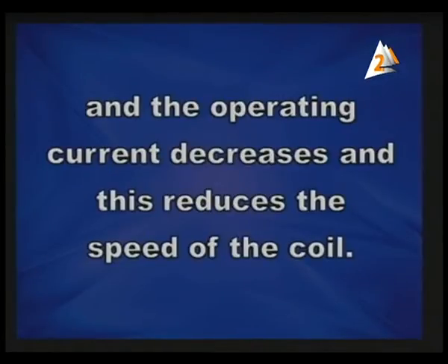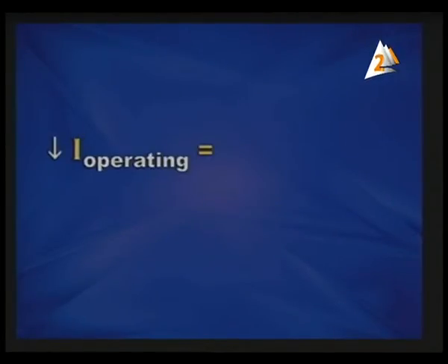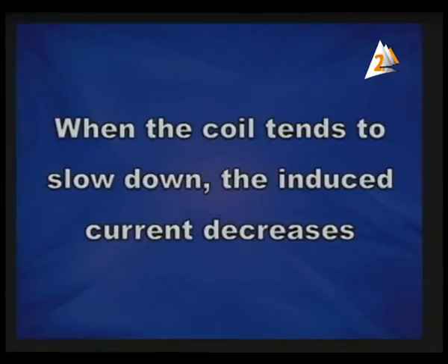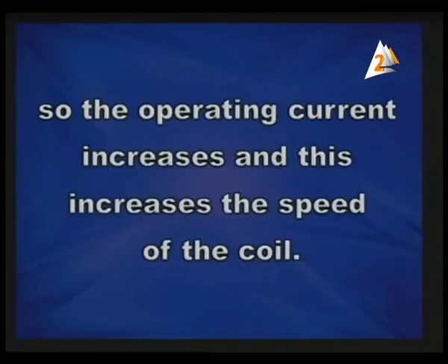As a matter of fact, it remains unchanged. So, once again, during rotation, if the coil tends to speed up, the induced current will be increased, and this will decrease the operating current. And when the coil tends to slow down, yes, the rate of cutting decreases, EMF induced decreases, current decreases. And what about the operating current? Operating current, of course, will increase.